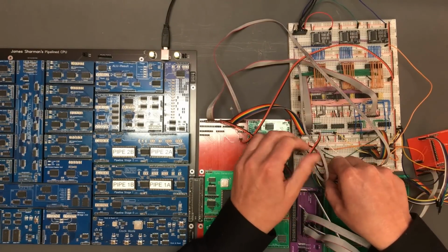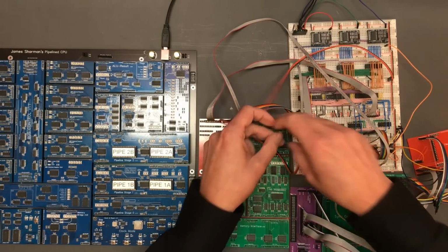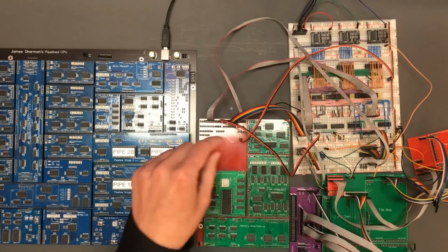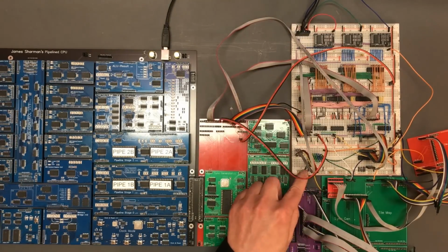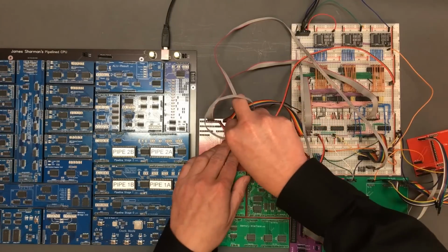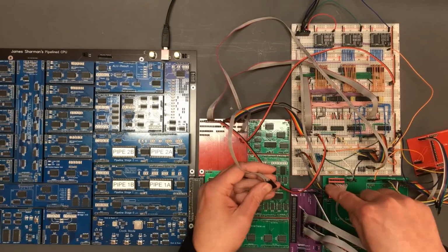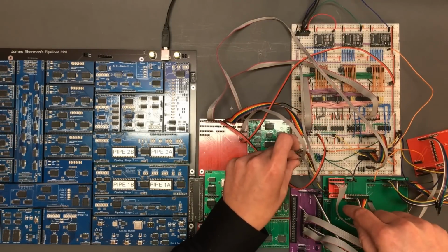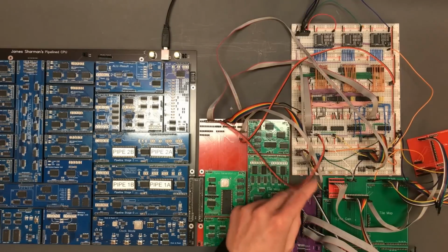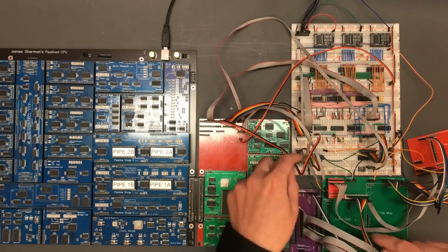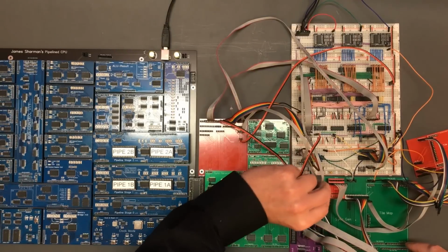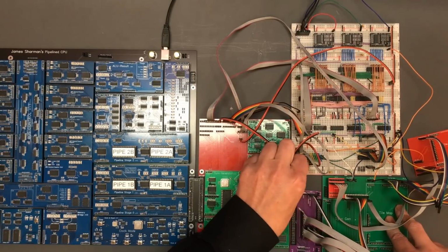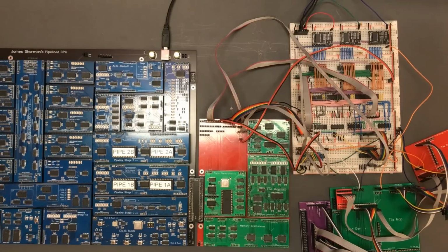So there are additional ground ties I've put in here. Let's put one there. Try and replace that with a longer wire in a moment. So here's the sync lines. Now in the last VGA video we actually swizzled those around a little bit. So I think the easiest thing for me to do would be to put this wire into the breadboard and then just reorder these accordingly. Now these orange wires are going to be clock signals.